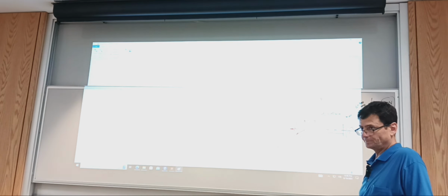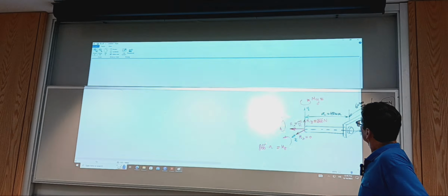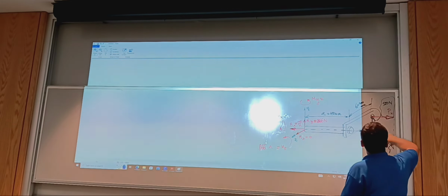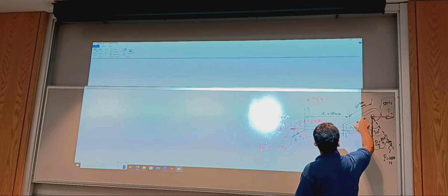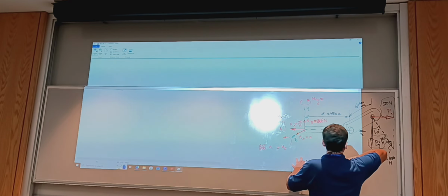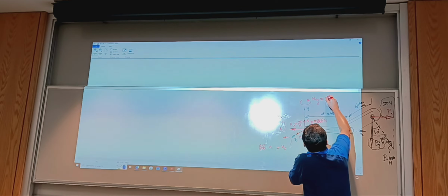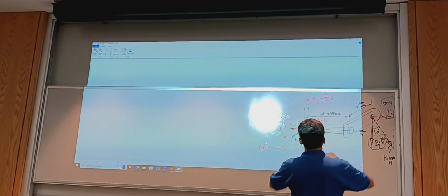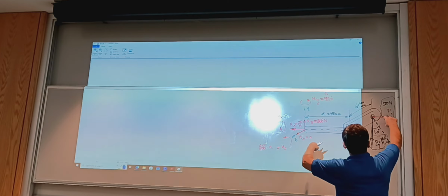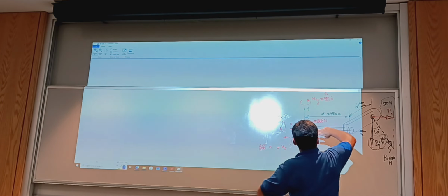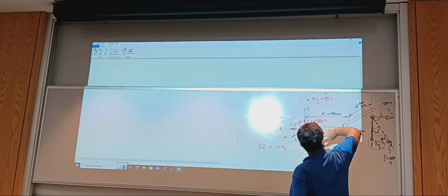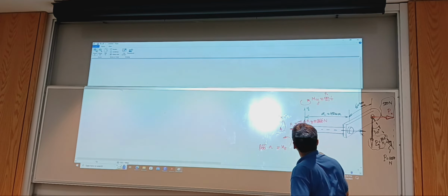Well, this moment is going to be equal to Px times B. Px is 500 newtons, times B. And in terms of its orientation, if you look at the part, due to this horizontal force, it has the tendency to rotate, right-hand screw: if you turn it, it goes down, and this is up.